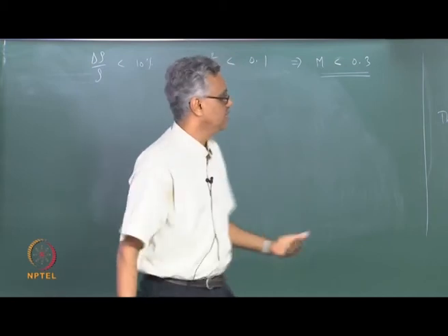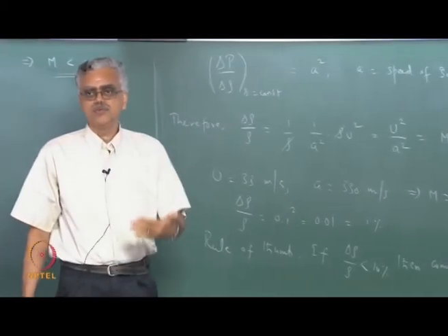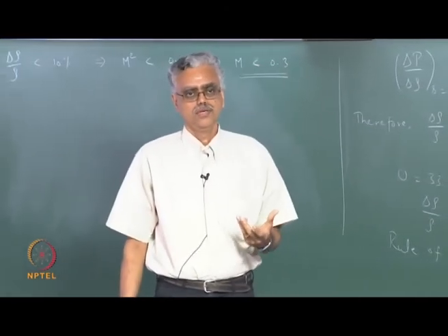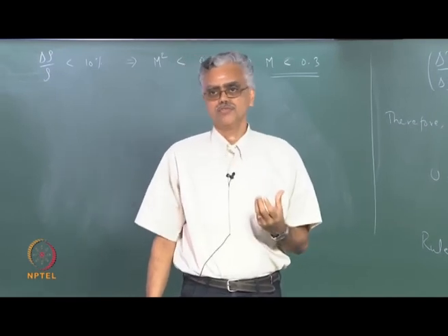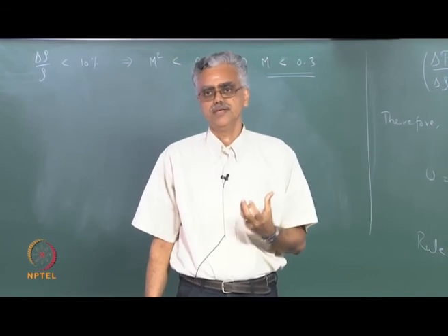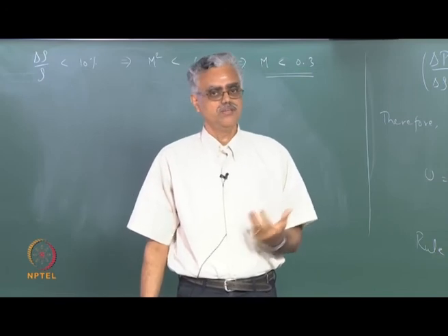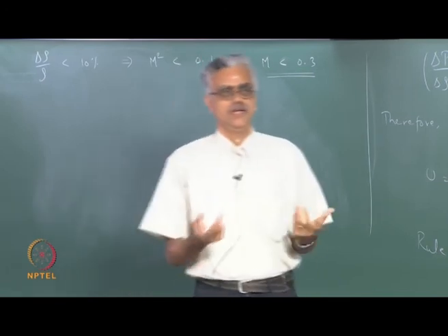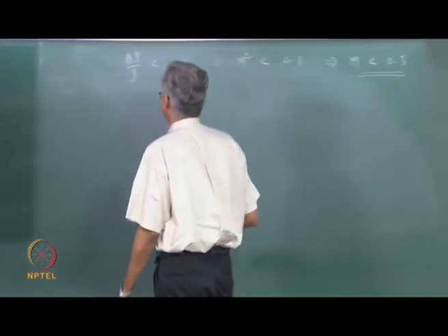The reason why speed of sound is important in these types of situations is that any disturbance that is generated in the flow field travels with the speed of sound. So when the actual flow speed is comparable to the speed of sound, then the compressibility effects are very significant, right. If the actual speed is much less compared to the speed of sound, then compressibility effects are smaller, right. So we said there are two criteria for assessing compressibility.